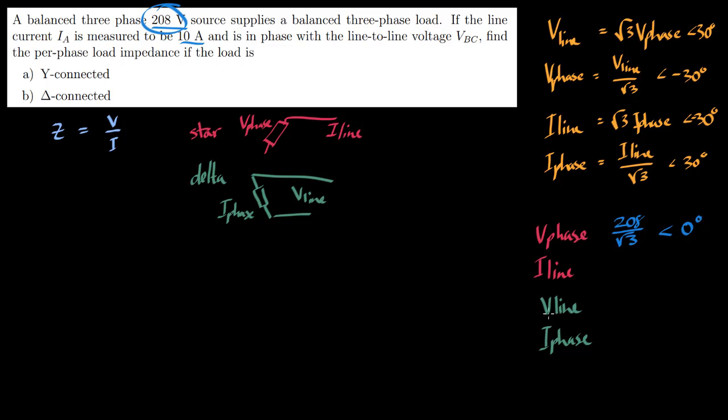To find our line voltage, we already have the magnitude, and we know from our formulas that it will lead the phase voltage by 30 degrees. For the line current, again, we know the quoted current magnitude will always be in line current. To find the phase angle, we have to complete an intermediary step of determining the phase angle of VBC.